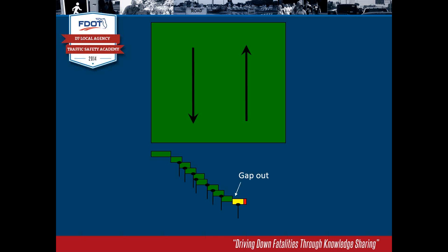And so if you arrived at an intersection where you see what the side street indication is, and you pull up to the left turn lane, if you get there just after it goes yellow, pull up in the conflicting left turn lane, you're not going to get your arrow. I know that's happened to me many times, but anyhow, that's how the signal is operating, how the traffic signal controller is thinking about the phase that's going. So it's extended based on those detections. If you get too big a gap between vehicles, it's going to gap out.